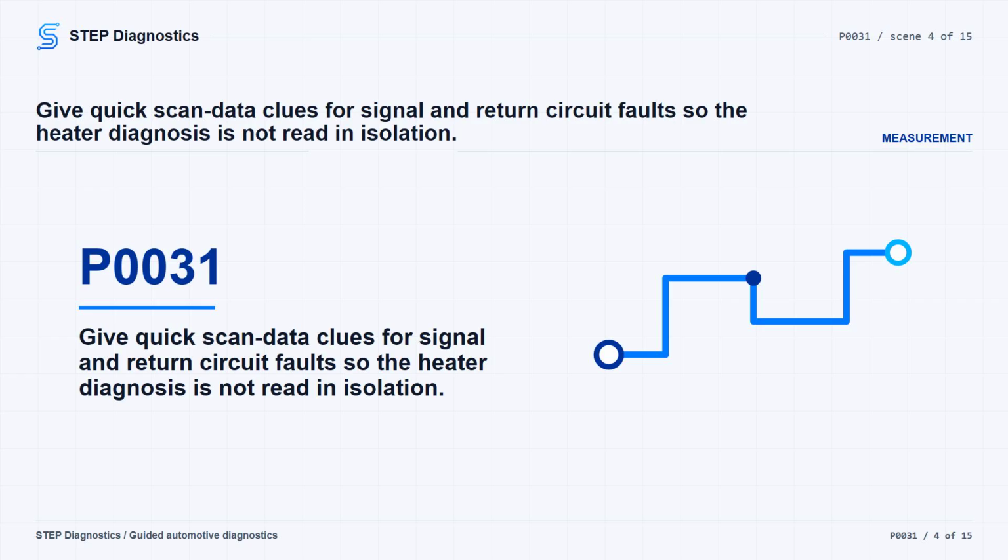With the O2 sensor signal shorted to ground and the sensor cold, the bias signal voltage will show 0 volts, while the 0-1 raw voltage signal will read -2.5 volts and increase toward 0 volts as the sensor heats up. An open in a sensor return circuit will cause the bias signal voltage to read high near 5.0 volts and the 0-1 raw voltage reading to be near 2.5 volts for the affected sensor or sensors.